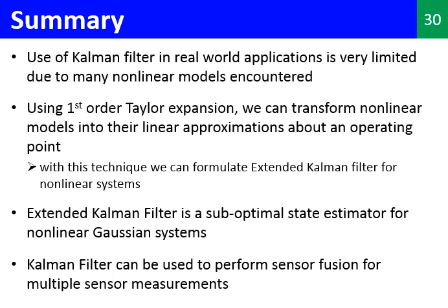We did that about an operating point, and we could formulate the extended Kalman filter for nonlinear systems. We understood that the EKF is a suboptimal state estimator for nonlinear Gaussian systems. And finally, we saw how we can use the Kalman filter for the purpose of sensor fusion. Thank you.